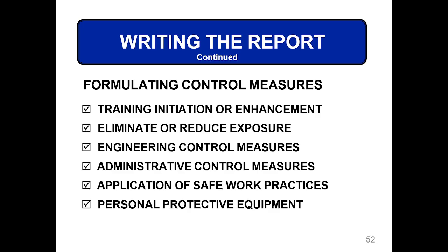And then personal protective equipment. They need to know, if you're going to work with electricity, what type of gloves. Are you going to use any type of gloves? No. What type of power are you dealing with? Is it high voltage? Is it low voltage? All these aspects. Are you dealing with capacitors or other electronic equipment? So it's very important to understand all this before you issue PPE.